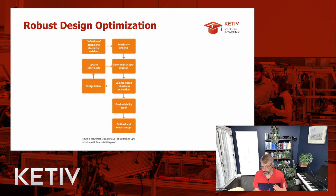But when you get to a variance-based robustness evaluation or Monte Carlo analysis, you might need to expand the total number of variables, because you were optimizing based on a subset of variables that you needed to focus on in terms of what was important. But then there might be other things that are important, whether it's loading conditions or material variability or different configurations that might cause you variance in the field, and you need to take that into account for your Monte Carlo analysis.